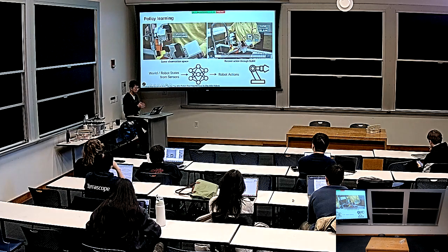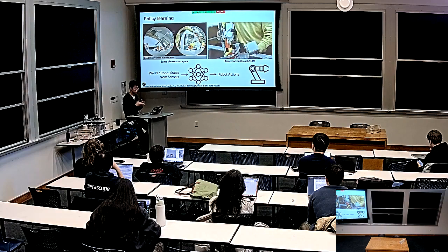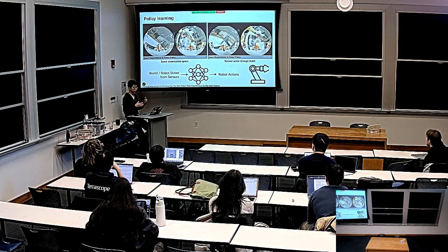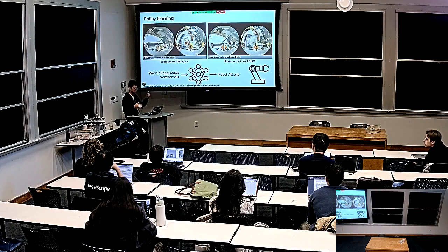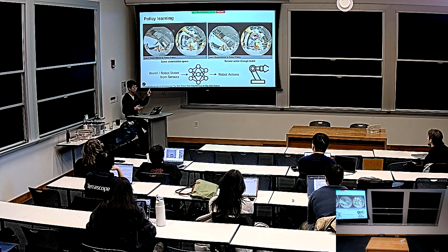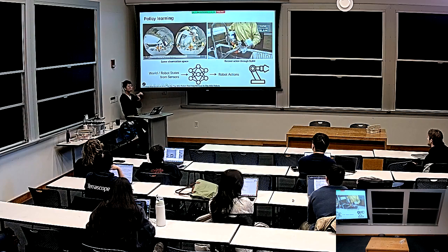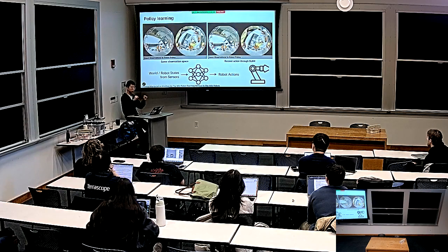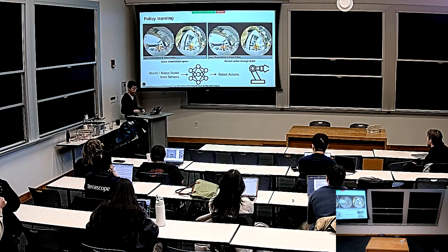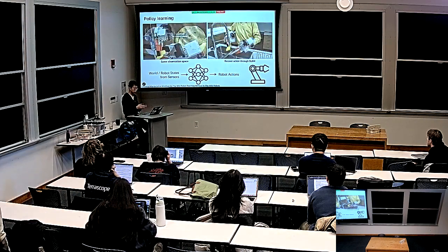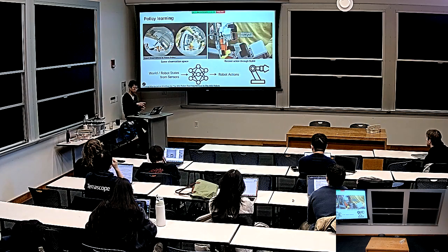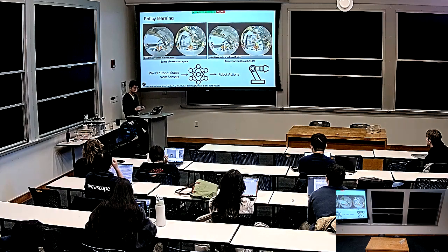Another way is, since we have aligned the observation space and action space, we can directly train the policy on the data collected by the interaction interface. In this UMI paper, they mount the camera on top of the gripper, which means for both the interaction interface and the real robot, they share the same visual space. And for the action, they just recover the 2 Cartesian poses from the IMU sensor on the GoPro.